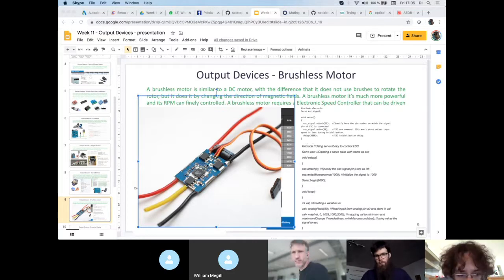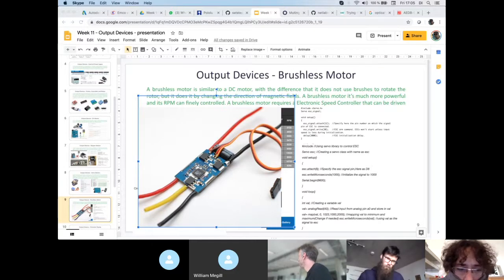So here we have the electronic speed controller. This in the center is a microcontroller. These 2 are MOSFETs, and you also have MOSFETs on the other side. And what it does, basically, it takes the PWM signal here as an input, and then through the microcontroller and the usage of the MOSFETs, these caps and so on, it gives the proper power signals to the motor to move.